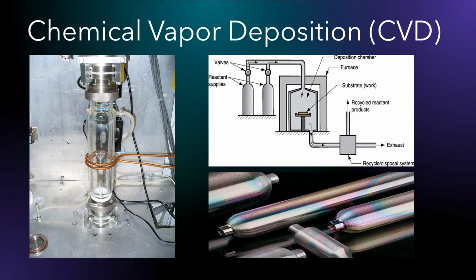Chemical vapor deposition involves the interaction between mixtures of gases and the surfaces of the heated part, causing a chemical decomposition of some of the gas constituents and the formation of a solid film on the substrate. The reaction will occur in a closed reaction chamber. The reaction products nucleate and grow on the substrate surfaces to form the coating, and most of the chemical vapor deposition reactions require heat. A variety of coatings and substrate materials are available.